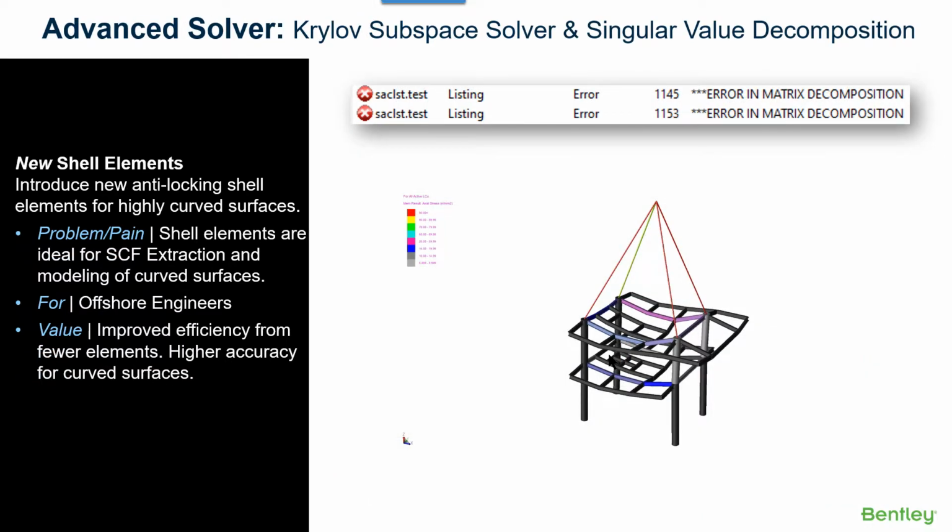And the next update is detecting and removing matrix singularity. As we know, if structures are not properly constrained in space, they show rigid body motions, meaning that we cannot solve the system due to the singularity. This is why we need additional boundary conditions, which are not real.